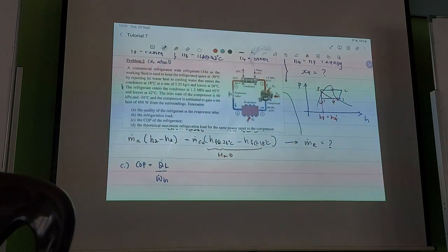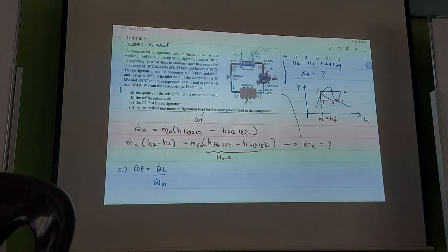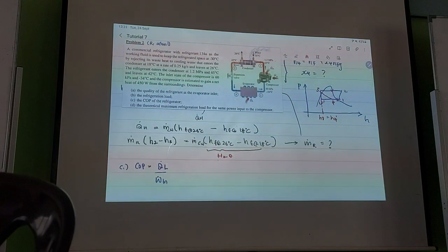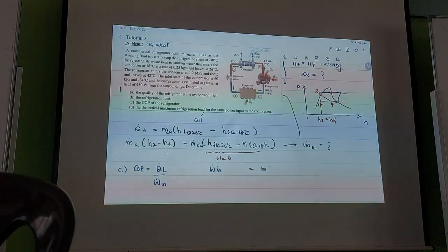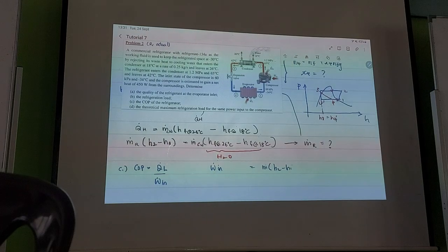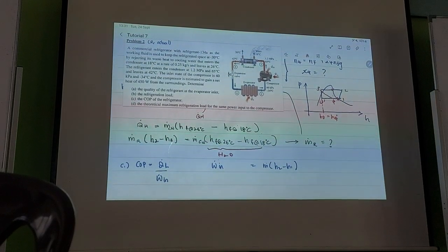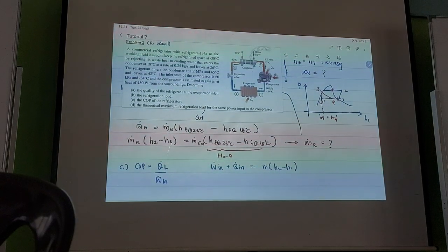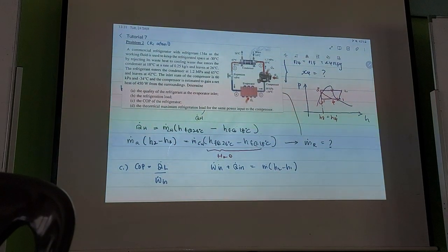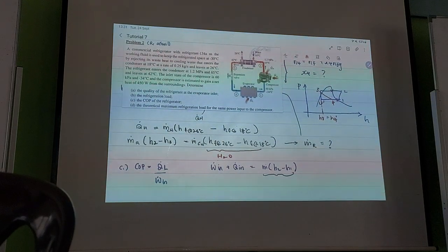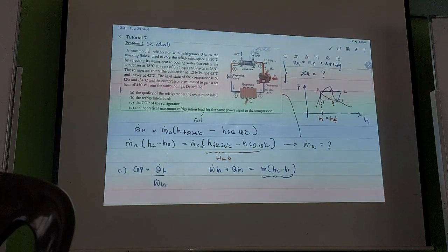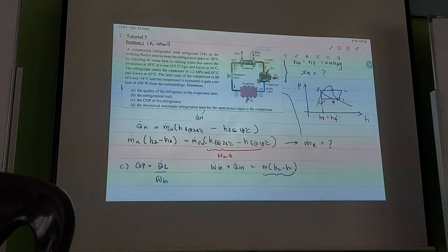This one cannot zoom in. If you look at the compressor here, do you see that there is a Q in the compressor? Which means that for this compressor, instead of usually saying work in equals m dot (h2 minus h1), this time we have this. Makes sense, right? Because this is the overall change in the energy, or what results in the change in temperature.